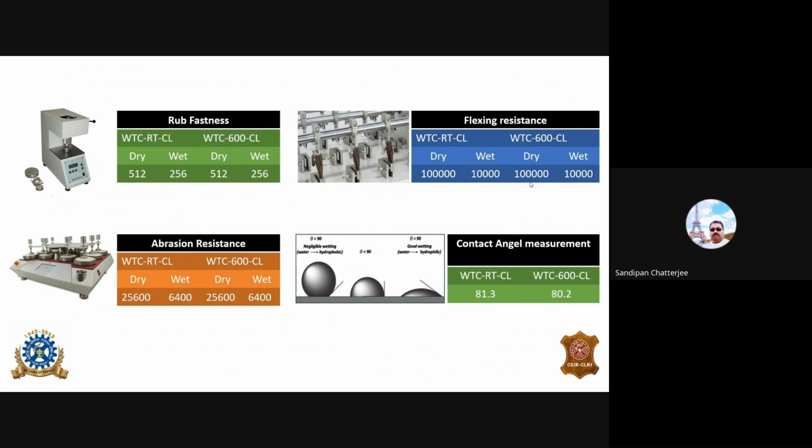And finally, we have done the surface hydrophilic property measurement by contact angle. For the one without calcination, we used the layer without calcinated toner, it has been 81.3, and after calcination it has been 80.2. It is very near to the ideal. It's neither hydrophilic nor super hydrophobic, but it is okay, and it compares well to other commercial products.